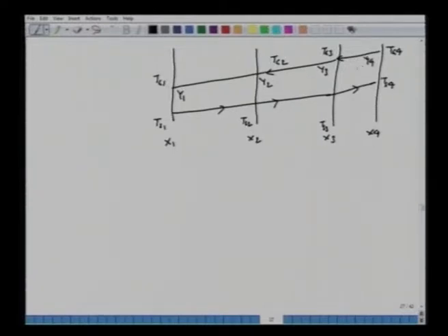All right. So before doing any calculations, we should draw this and see what is given to us and what is not given to us. X1 is given to us, let's put a tick here. X2 is given to us. X3 is given to us. X2 is nothing but Xc, the critical moisture content. And X4 was given to us, but we said that X3 equals X4 because this is region 4. So all 4 moisture contents are known to us.